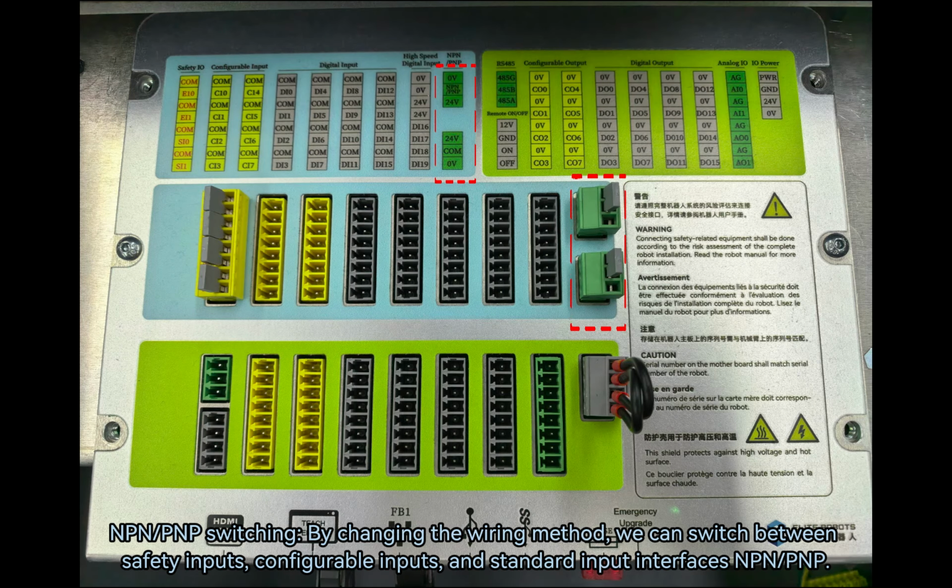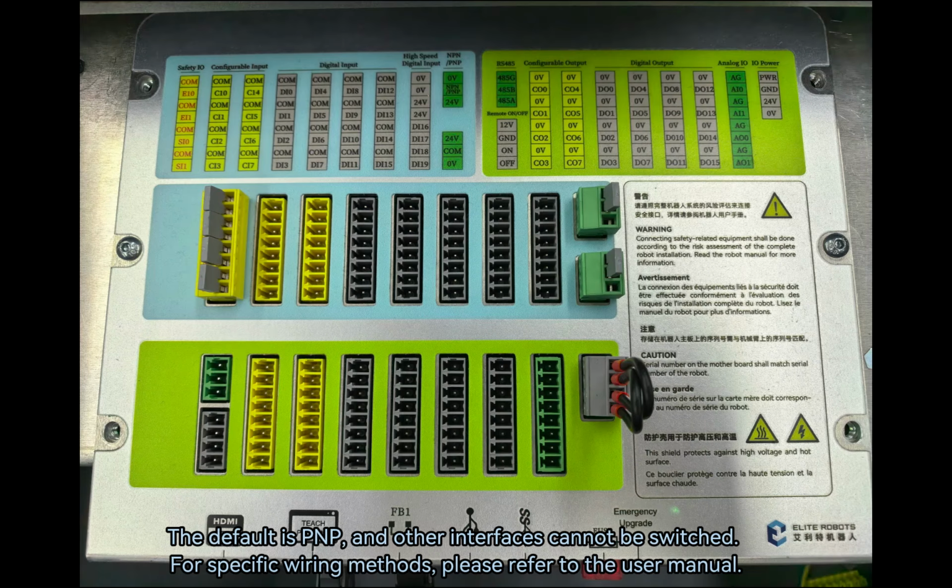NPN or PNP switching. By changing the wiring method, we can switch between safety inputs, configurable inputs, and standard input interfaces NPN or PNP. The default is PNP, and other interfaces cannot be switched. For specific wiring methods, please refer to the user manual.